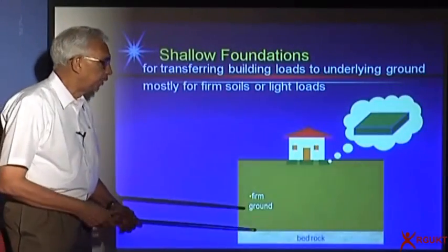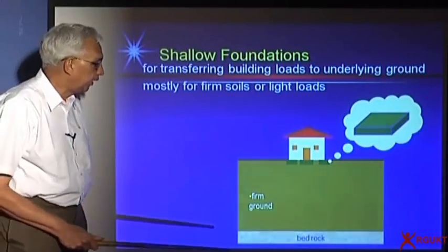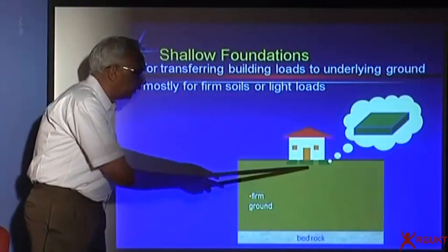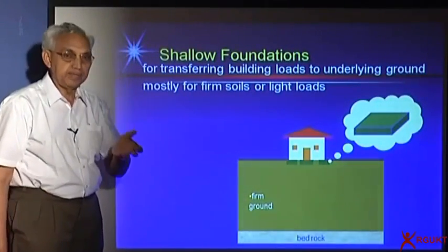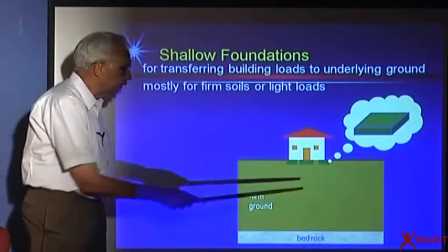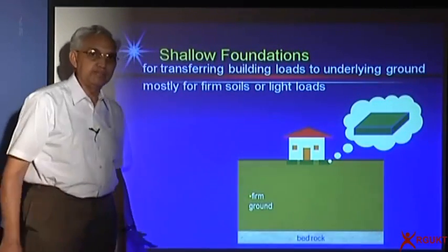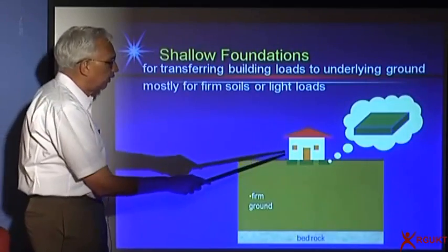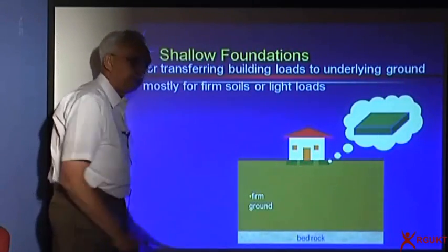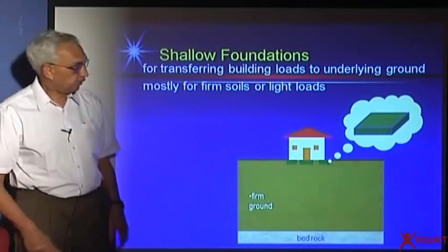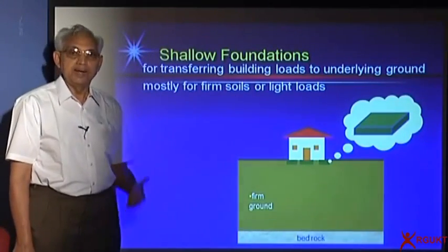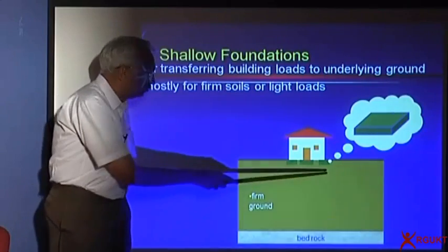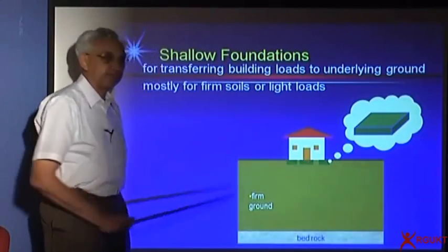Look at this small building or a medium-sized building, but the main thing is the ground here is reasonably good. For example, if you happen to be in Hyderabad, in most of the areas you get very strong, stiff ground, in which case we are able to just dig up maybe 1, 2, even multi-storied buildings. They are able to go to 3-4 meters. Unless they want a basement, they put the foundation here and construct it.